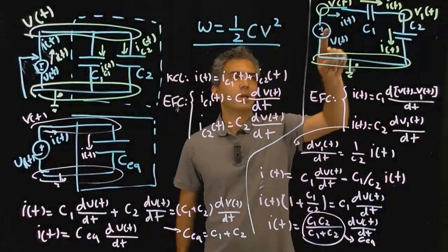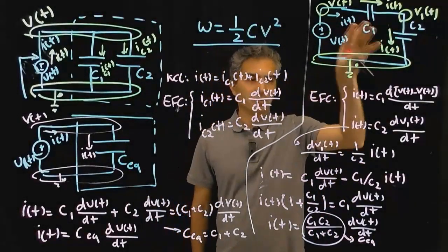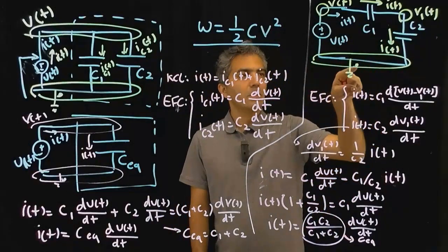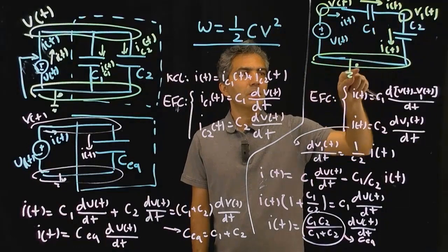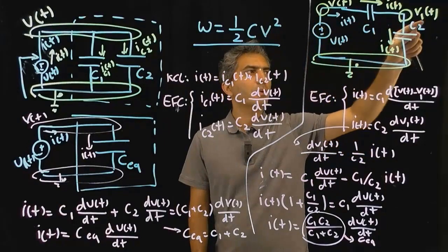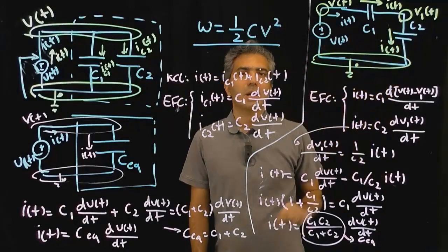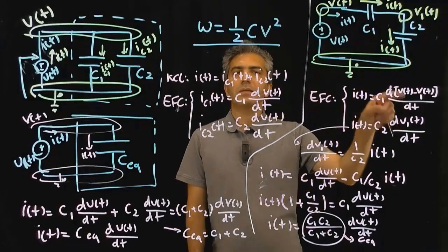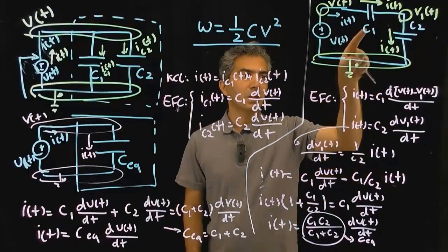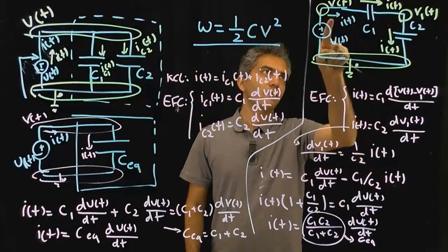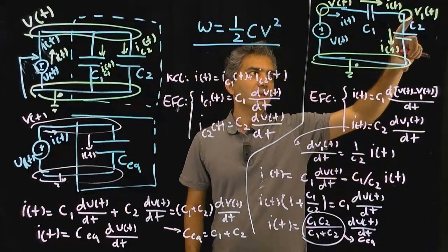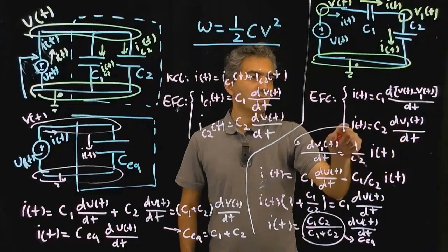So, okay, when you put the capacitors in series, I just wrote it down so that we can quickly go through it. We do the same. We label the circuit, and I call that my ground or zero. That's VT from the equation for that component. I call that V1, and the same current is passing through all three components. There's no KCL to write for that circuit. I only write the equations for components. So this is the equation for that component. Notice that the voltage across that capacitor is VT minus V1T, and the voltage across this capacitor is just V1T minus 0, so these two.